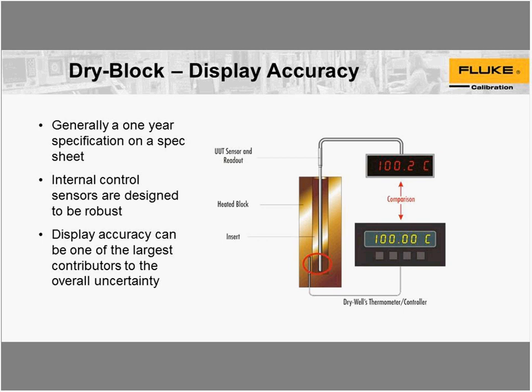The other thing that I've seen cause problems is when you're removing and inserting the wells or inserts of the unit. You want to set these in gently and avoid getting it partially in and then allowing it to drop. That can cause a physical shock to the sensor.